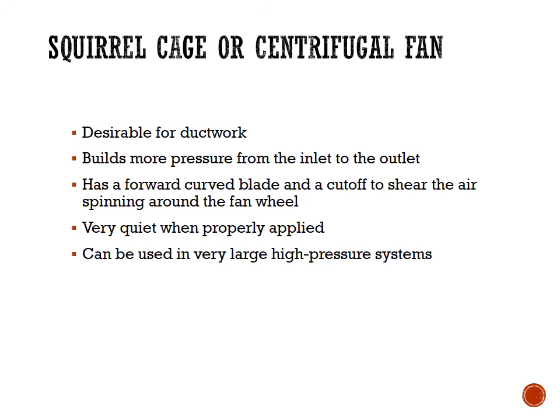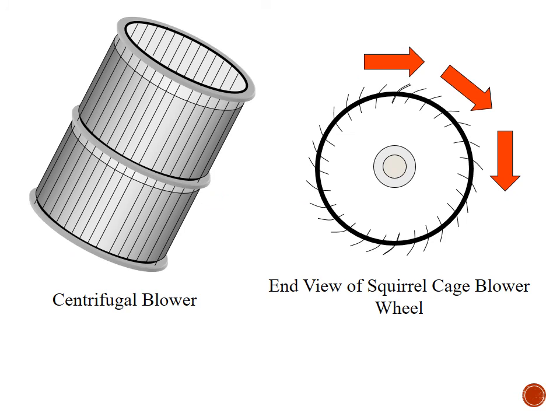There's either a squirrel cage fan or a centrifugal fan, different kinds of fans used in the duct system. This just describes different types of fans that we can have. It's an example of the squirrel cage fan. It provides a lot of pressure, and the volume dispensed by that fan compared to the noise is very efficient, and those also can fit in very small tight spaces.